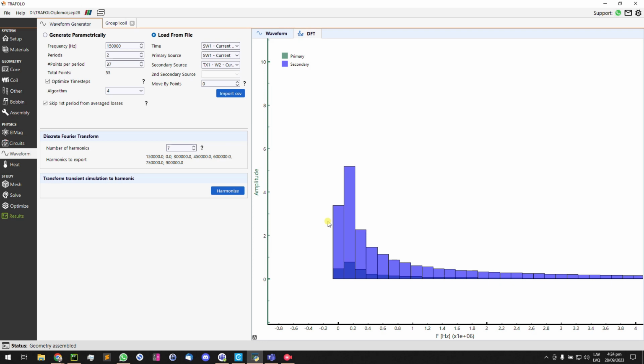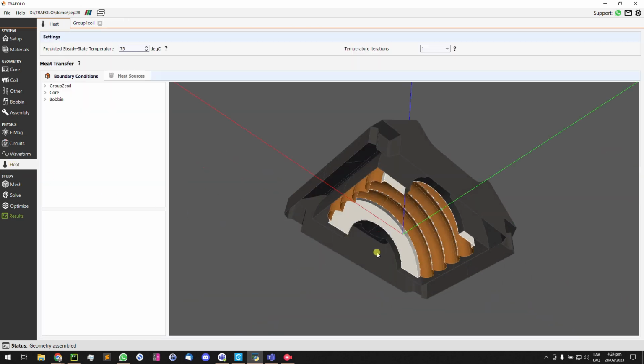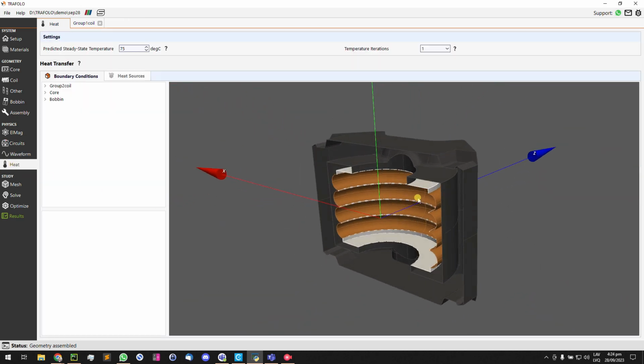topologies with signals or excitations close to sinusoidal, if you, for example, have one sinusoidal base frequency with high amplitude, a pure sinusoidal, and then you have some additional noise, then you would better go with a harmonic simulation, where those frequencies will be solved independently of each other, and then those losses would be summed together.